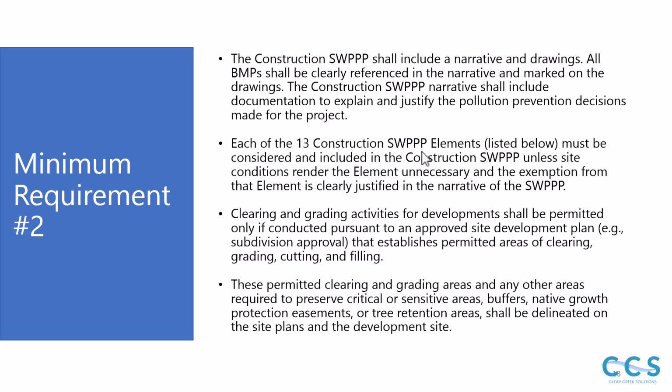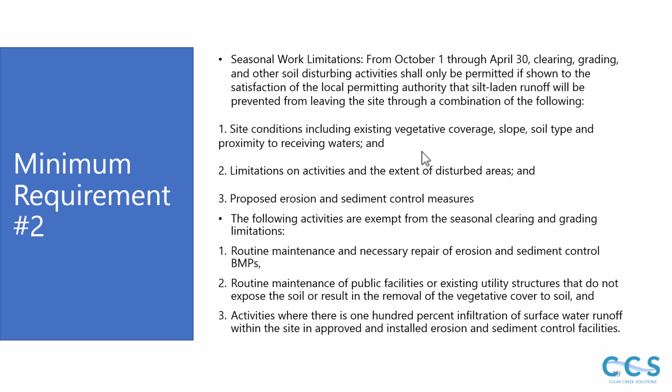Clearing and grading activities for development shall be permitted only if conducted pursuant to an approved site development plan, e.g. subdivision approval, that establishes permitted areas of clearing, grading, cutting, and filling. In these permitted clearing and grading areas, and any other areas required to preserve critical or sensitive areas, buffers, native growth protection easements, or tree retention areas shall be delineated on the plans and the site.